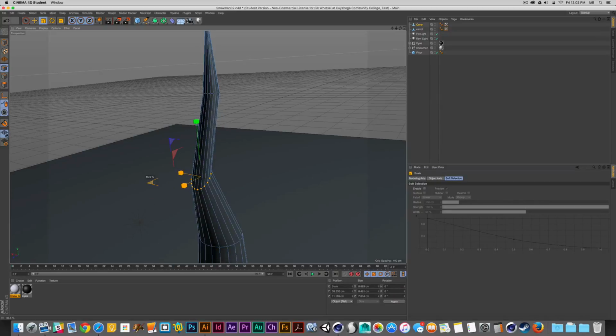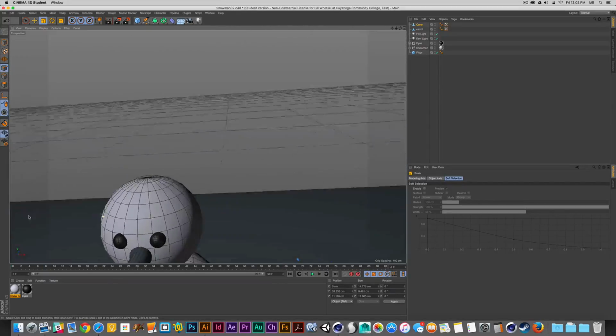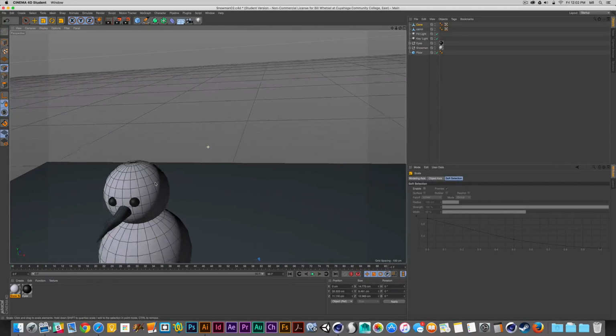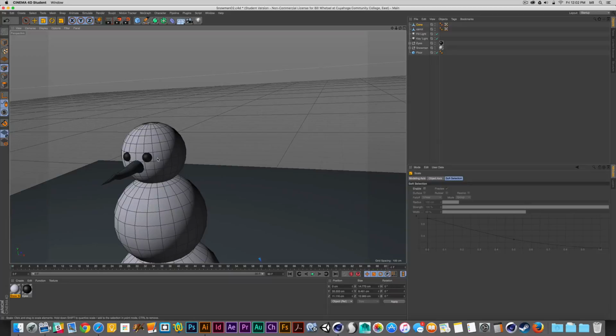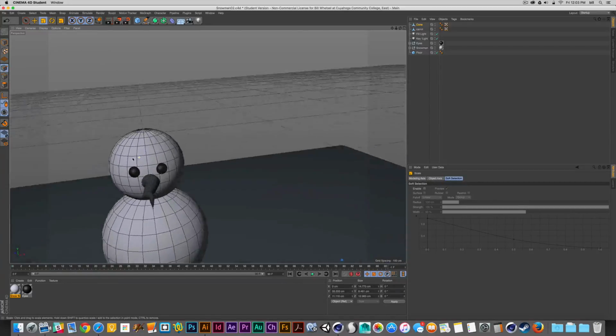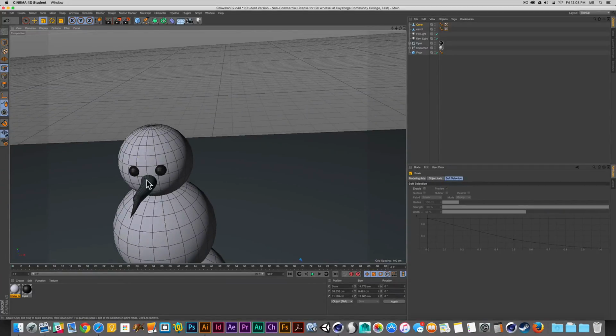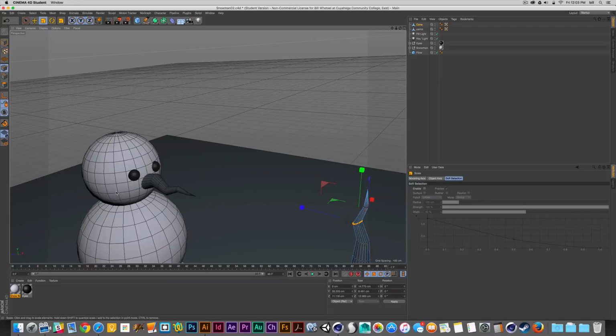Okay, so I don't really want to scale my carrot, but I do want a couple of options. You can see that sometimes when I navigate, I'm kind of flying around, and that's because it's orbiting around the point at which I click to orbit. Okay, so because I'm using this option click method, I'm finding myself in a situation where I'm not orbiting necessarily in the center of the scene. I'm orbiting based on what I click on. So I want to make sure I option click, and then I'll orbit around that point. Okay, so that's getting a little hard to navigate. Just make sure that you have an object in front of you. I'll share some other methods with you in the near future about how to navigate the scene.